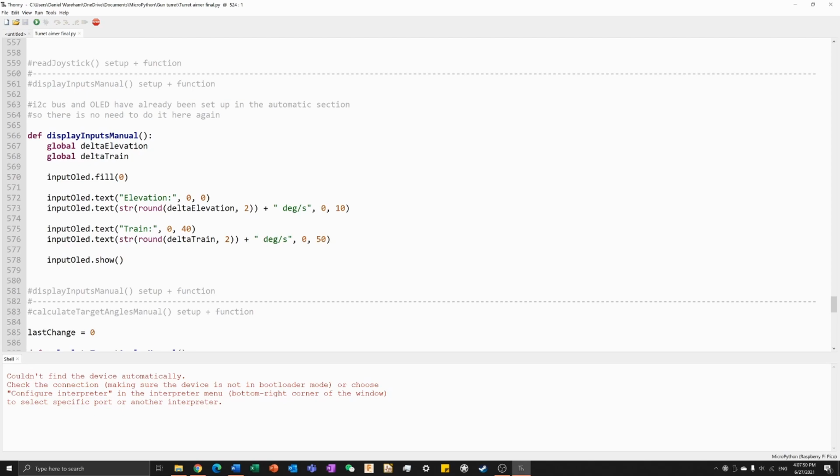Just knowing the speed that the servo has to move isn't enough, however, because the output to the servo is the output in terms of position. So the processor itself needs to know the speed and do calculations with it to set the target position that actually gets sent to the servo to be moved to.